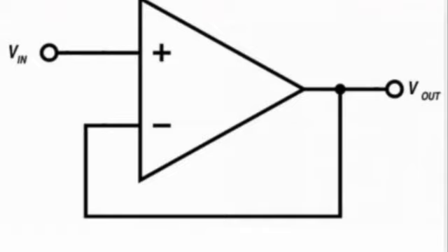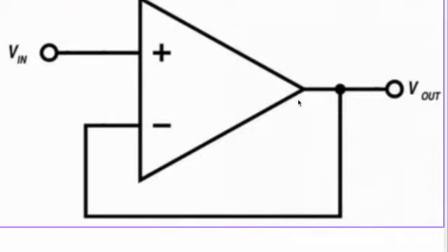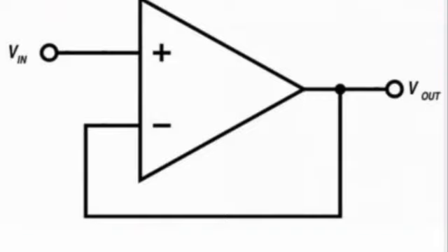Essentially, the voltage follower ensures that the DAC's analog output remains accurate and stable, and unaffected by any variations in the next stages of the circuit, which would be very useful if you want to connect the circuit into something else. That's it for the R2R DAC.